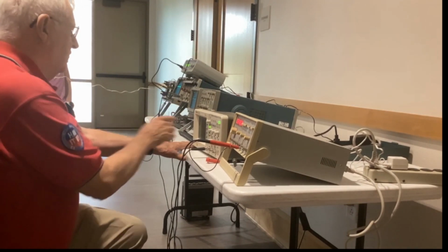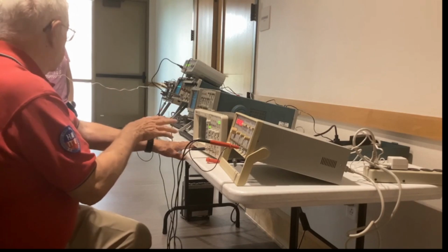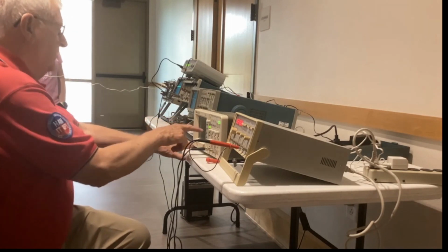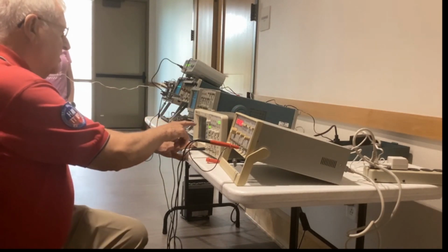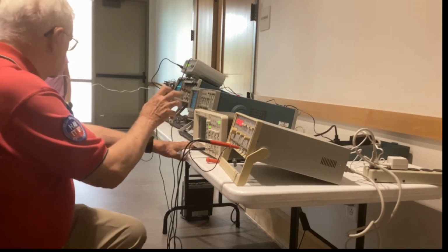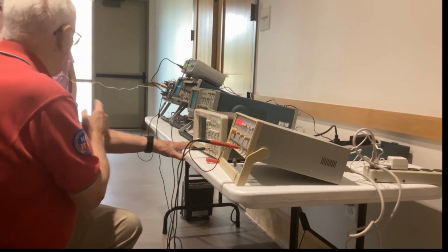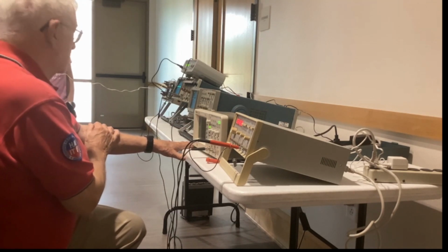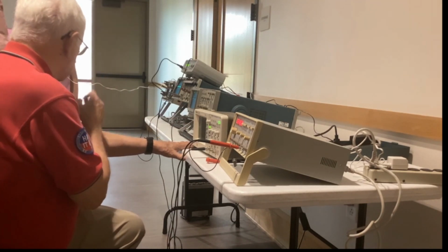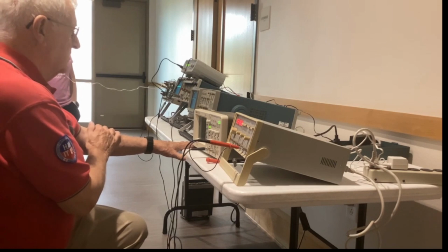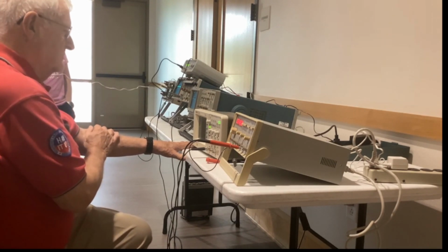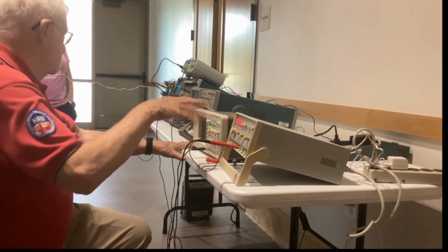So if you're doing a whistle into your microphone, and you got that, oh, that's perfect. But if this thing is clipped at the top or it's really distorted, then we got a lot of distortion in our audio. Bad microphone, gain is not set right, or there's something in the audio amplifier for our speech that is not right. So there's all kinds of different ways for using that sort of stuff. This is just demonstrating it, as I said.